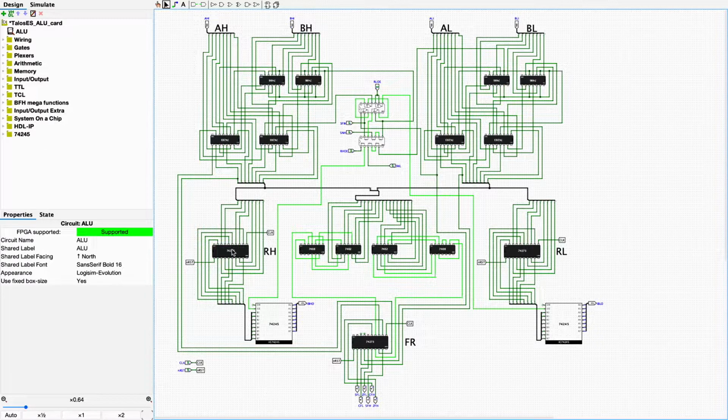So that's the reason why these registers here are local and dedicated. You cannot program the result of the ALU to go into any other register other than the 2 registers that are dedicated to it. And from there you can move them elsewhere in the next instruction, in the next cycle. That's the reason. So this is pretty much it.